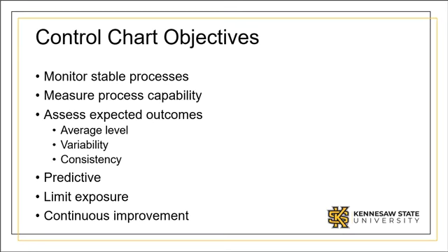Control charts can also be used as a predictive tool to determine when adjustments will be needed. When producing in lots, once an issue has been found, we have no choice but to re-examine or scrap the entire batch lot. Using control charts gives us the additional signals to stop the process at the instant an issue is found and localize our examination to only the parts produced since the last check. This significantly reduces the amount of potential suspect material.